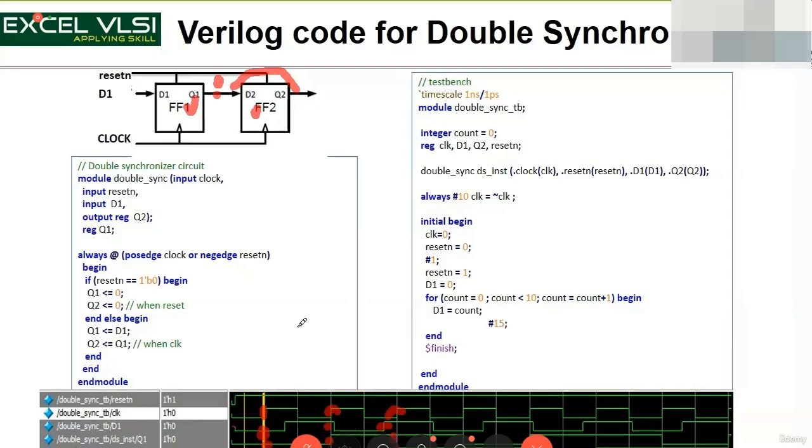So the takeaway here is how the synchronous circuit, the flip-flop timing, works. Now, all these delays, from D1 to Q1, D2 to Q2, right now they are ideal. I have not considered any delays. It is a functional simulation. I have not considered any delays here. So with this background, further, here itself, if I want to explain the setup time, the setup time is before the edge of the clock.